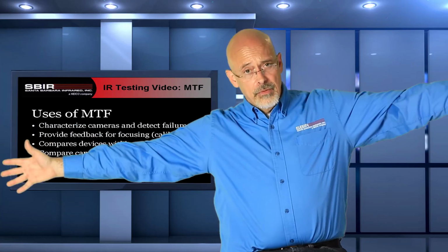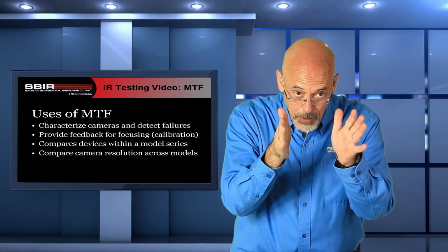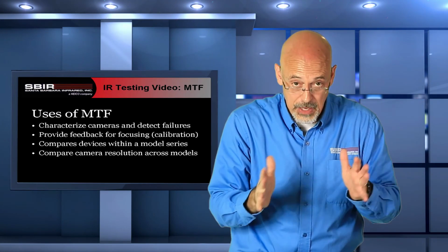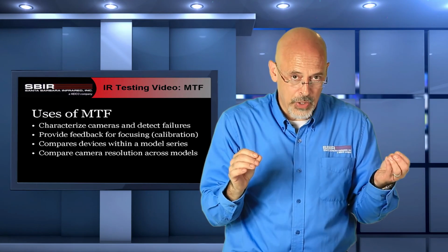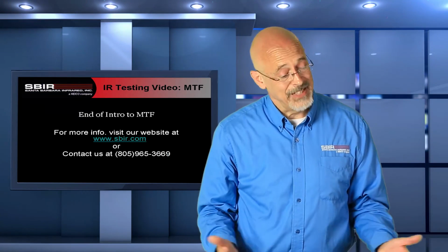If we are trying to get a big picture of an entire battlefield and we're looking for missile launches, that's very different than if I'm looking for a person that's coming at me to be able to identify if he's a friend or foe. So our MTF requirement varies depending on the task we're trying to accomplish. And as long as we are aware of that, then we can pick out the camera that has the MTF most appropriate for the task we're after. And that's MTF.